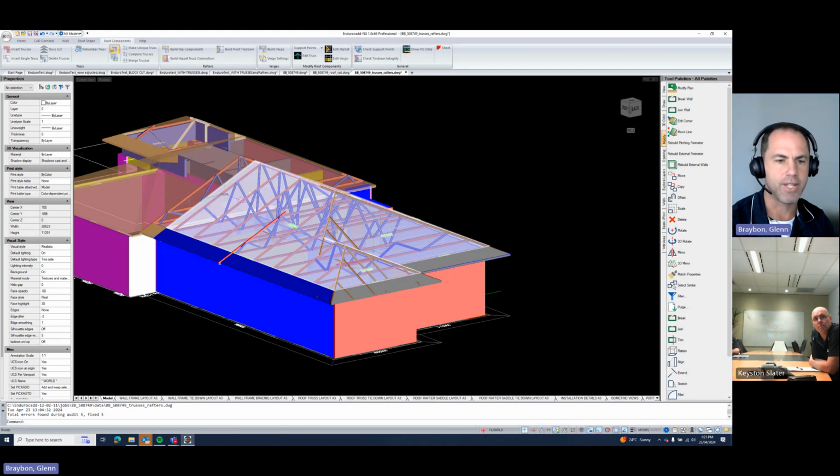similar to what you guys do with your C250s, and then you step that truss around with the eaves of feet coming in with your 3 courses. Maybe we'd work on a 254 high beam or 257, I think your 3 courses are. So then you could utilize that wall frame beam to line up with your eaves of feet, and it might span 2 or 3 meters, and maybe for some of your porches we could use a quad stud or a double stud section in there, and we maybe just not need those C150s or C250s. Yeah. Get rid of purlins altogether.